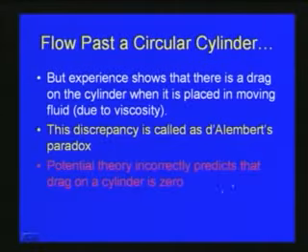This is the experience, that there is a drag on the cylinder when it is placed in a moving fluid due to the viscosity. So, when we analyze these kinds of problems with respect to the potential flow theory, or the superposition of the elementary flows which we have seen so far, some parameters are not obtained properly or are under predicted, like drag force is 0 here and lift force is 0 here, which is not realistic when we consider the real fluid flow where the viscosity is also considered.